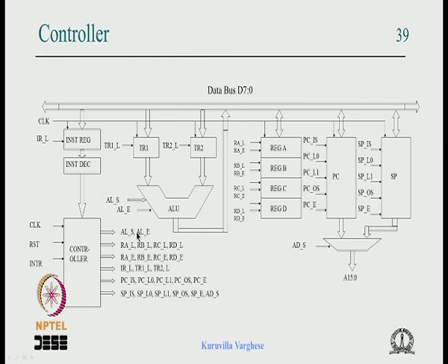We have seen in the slide an example of the CPU, and as I said, the controller's job is to give control signals to this data path. We have taken an example instruction, adding A and B and putting the result back to A, the execution part of it, but that is enough for analysis. So essentially it means moving A to this register, B to this register, selecting the operation, and moving the ALU output back to the register A.